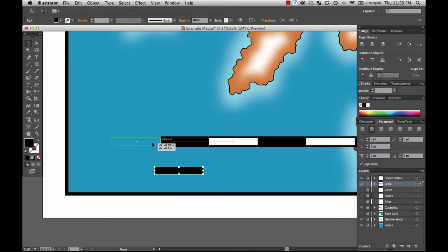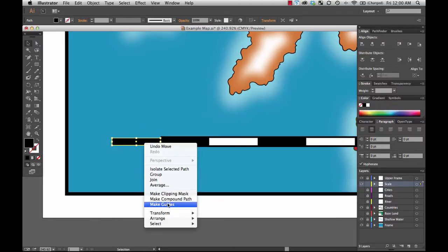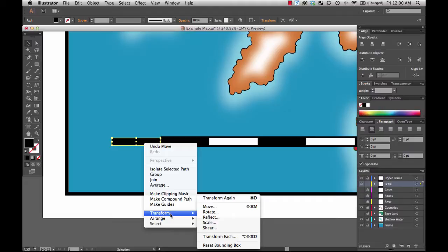So I'm going to put one division before the 0, and then I'm going to subdivide it into different groups. You get to decide exactly what you want to do for your subdivisions. Maybe in this case, depending on what the purpose of this map actually was, it would be appropriate to divide that into 20-mile increments. I can very precisely do that. Now here it's not too difficult because I know that's exactly 1 inch. But this is one of those situations where scaling a non-uniform scale will really help you out.